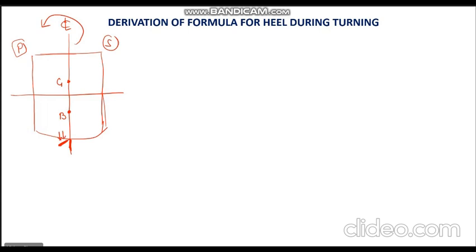Yes or no? Exert force on the rudder. Okay. Now, one, it will affect the speed of the ship. Second, what will it do? It will also have a transverse thrust. Do you think this will cause a transverse thrust to starboard side or port side? Look at the force acting on the rudder. The sideways thrust, will it cause it on the starboard side or port side? If you are turning to port, then starboard side.